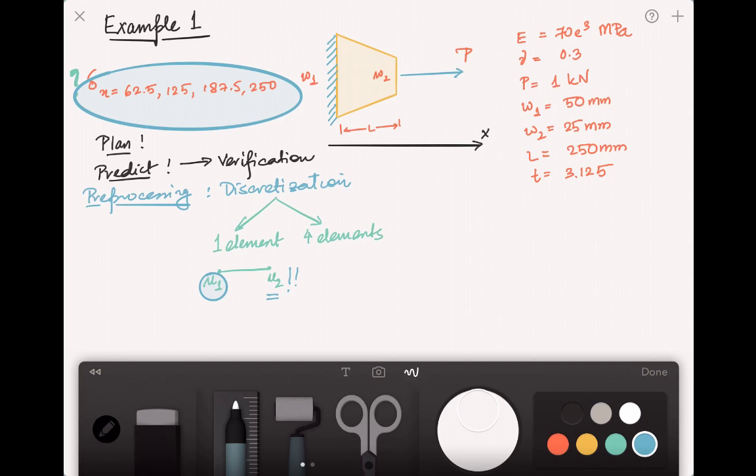different locations. So although this is a correct discretization because it's just a bar element, a linear bar element, and if I divide it into one element or four elements, I will get the same results. The only thing is I can't extract the results because it's not calculated across the element, but only at the node. So I'll have to do some extra post processing. To save that effort, I can easily divide it into four elements.